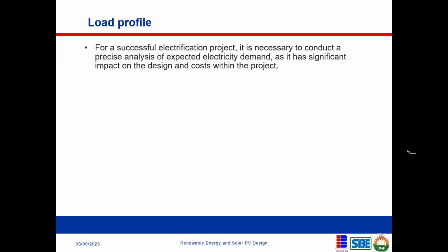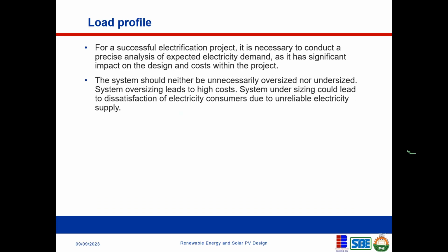For a successful electrification project, it is necessary to conduct a precise analysis of expected electricity demand, as it has significant impact on the design and cost within the project. So when you want to do a PV project, sometimes you may want to do a load profile. If you have a load profile, fine. But of course, we know that we are not very good with data in Nigeria. But if you have a load profile, that will be perfect. You look at the load profile and look at the peak.